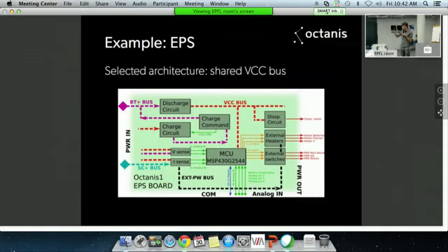If the power bus drops below 3.3 volts, it gets regulated or stabilized by discharging the battery or by solar power, but you cannot steer this. And if it gets higher than 3.3 volts, it is regulated again by charging the battery. That was the main concept that he then implemented.